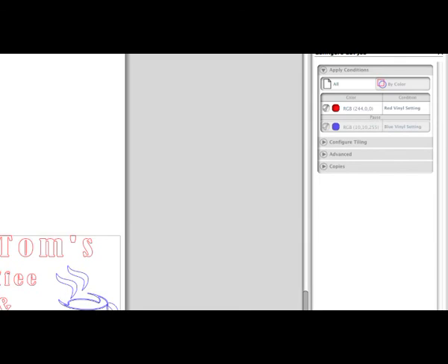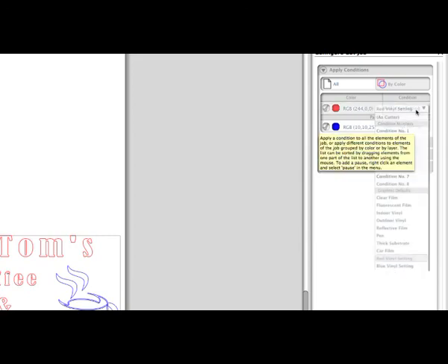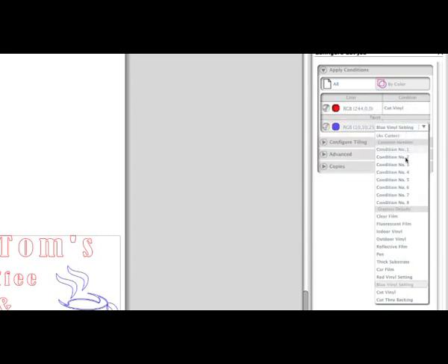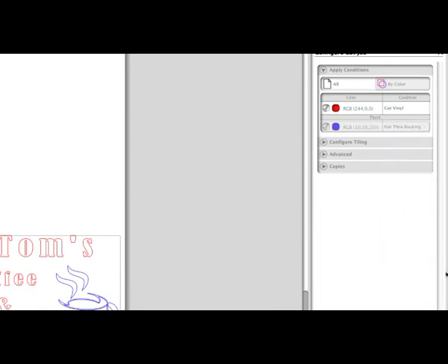This may be helpful when having 2 different types of material that need alternate settings. Some have used this feature for the print and cut process by assigning one cut line color for cutting through the first layer and assigning the second color to a condition for cutting somewhat further into the liner sheet for pop-out decals.